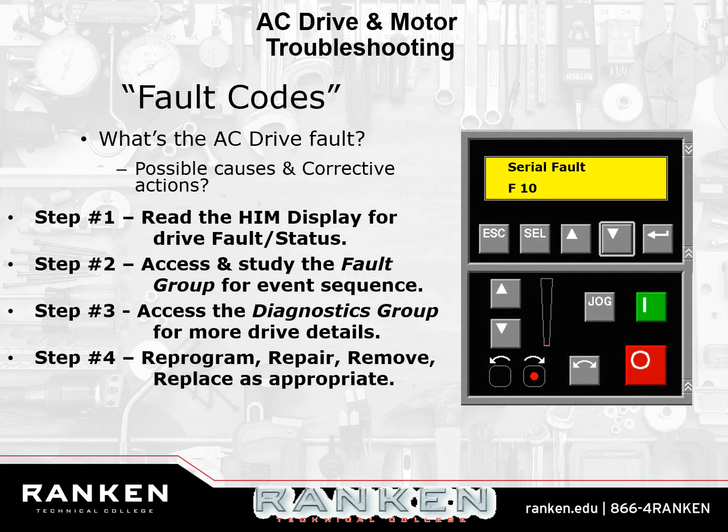Check the fault codes of the drive. When we get into the shop finally and we start talking about doing troubleshooting on these drives, trying to figure out what's going on, I'm going to show you how to do it in a methodical way. For now, just understand that you need to check the fault codes. This will sometimes point you right to the problem. Sometimes, like I said, it can be really ambiguous, and it'll just say DC bus voltage. It won't even say if the DC bus voltage is too low, too high, or anything. It just says DC bus voltage. And you're like, well, what do I do now?